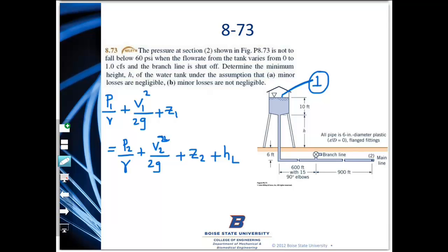So you can see that P1 goes to 0, V1 is 0, and you know why that is. For now, let's make sure this P2 is at 60 psi, and let's pick our datum at Z2. So this is our datum.